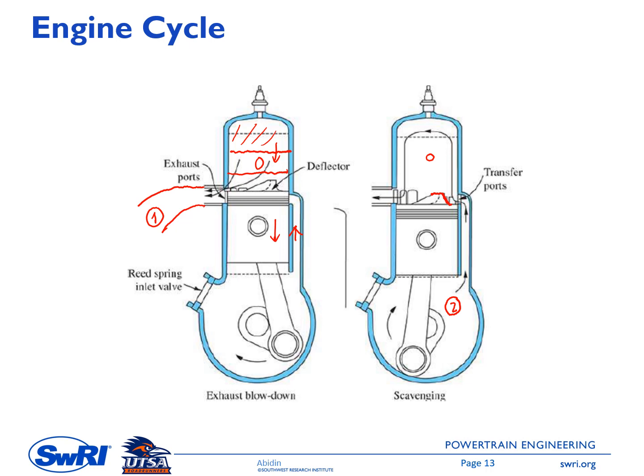In the scavenging process, the fresh mixture displaces the exhaust gas. Usually we have a special design of the cylinder head that can direct the fresh mixture following this arrow and then going down and displace the exhaust gas. And then the piston is at bottom center, the scavenging process continues, and once the piston hits the bottom